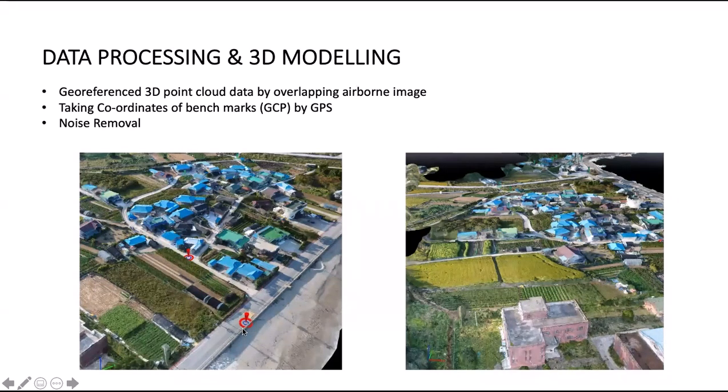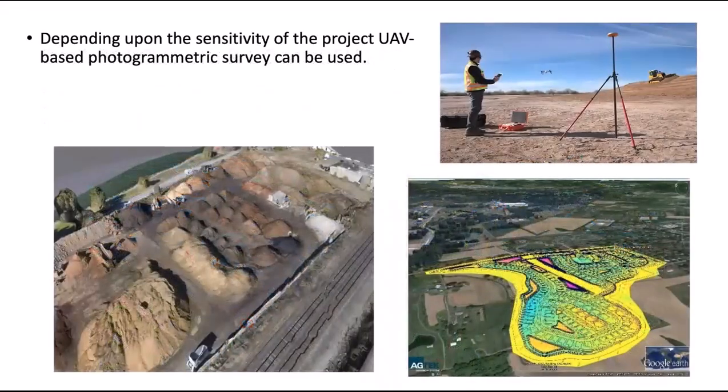So you measure XYZ using some technique which is more accurate, maybe using traditional survey, or maybe using RTK GPS. So just measure these 7 or 8, 9, 10 points. Don't go more than 15 in one project, and it should not be less than 8. Otherwise it can compromise your accuracy. Okay, it should be more than 8 and less than 15, and you can just calibrate them with your model, so it will make them more accurate.